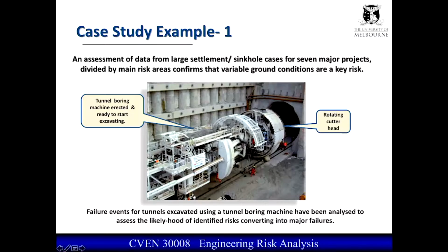And there are cutters on the head cutting out small pieces of rock, and those small pieces of rock get taken out on a conveyor system through the centre of this. Behind this cutting head, there's a framework where you can put up steel or concrete support, usually called a temporary support, whilst the tunnelling is going forward. And once the machine has disappeared, you come back and put in permanent concrete and so on. That's what you see when you see the finished tunnel.